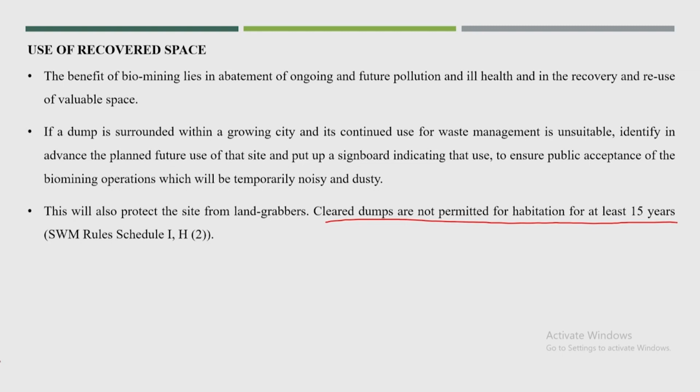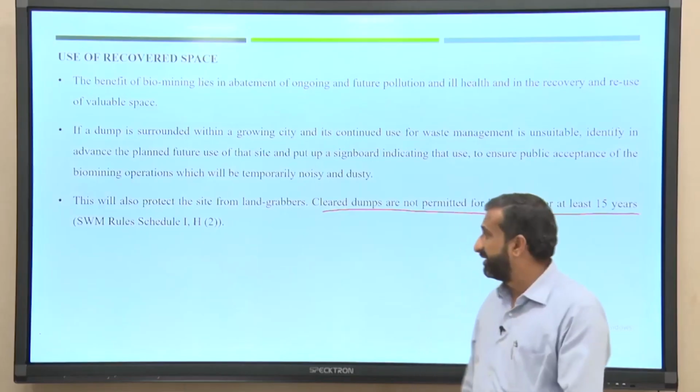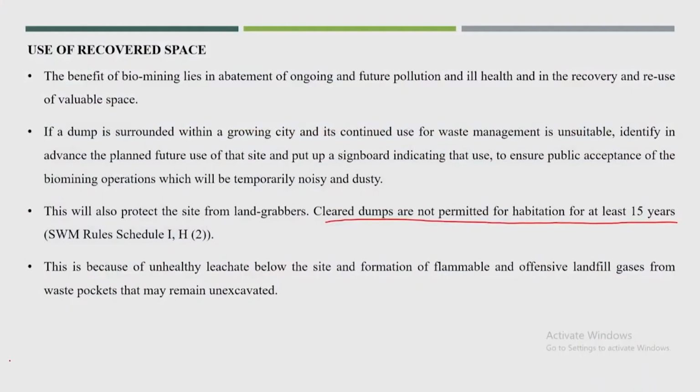This is based on the SWM Rules, Schedule 1 H2, which specifically says: cleared dumps are not permitted for habitation for at least 15 years. Whether it is very close to the city or at the center of the city, it should not be used for any habitation. This is because of unhealthy leachate below the sites and the formation of flammable, offensive landfill gases from waste pockets.